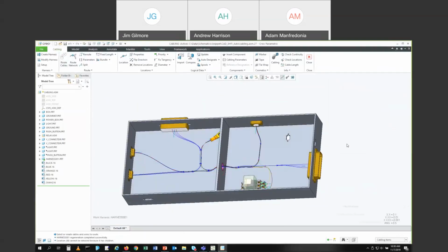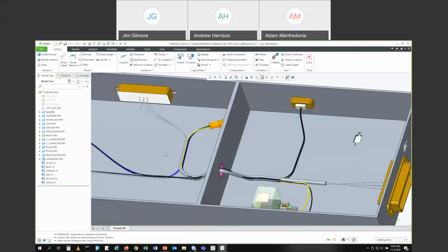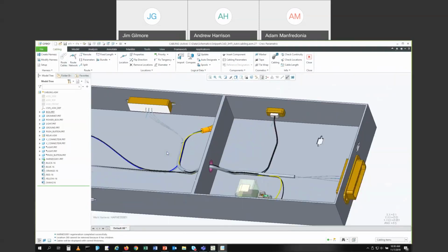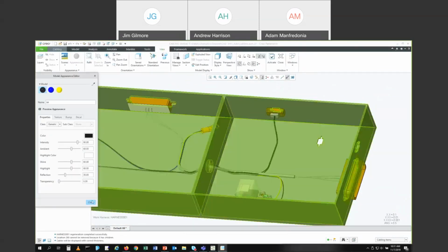At that point, I'm just going to hit accept. I'm going to shade this out, and you're going to see that even the wires come in at the correct color. If inside of the spool I have color set, and I have that color set inside my color map inside of Creo Parametric, it'll automatically associate that color in here. So if I come through to view and I look at my appearances...